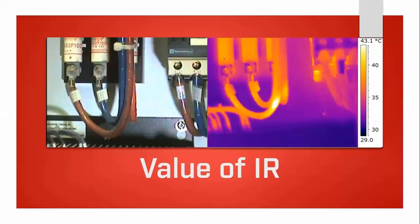In the thermal image, if white is hot and black is cold, the phases themselves look balanced, so there's no real temperature difference between them. If we take a closer look at the brown cable, we can see that there's a thermal anomaly. At this stage, the camera doesn't tell us what the problem is, only that there is a hot spot or area. And it's the experience of the camera operator which will shed light on the problem. If you're a consultant, detecting the problem is probably as far as you want to go. You found a problem, so you leave it with the customer to diagnose and repair.